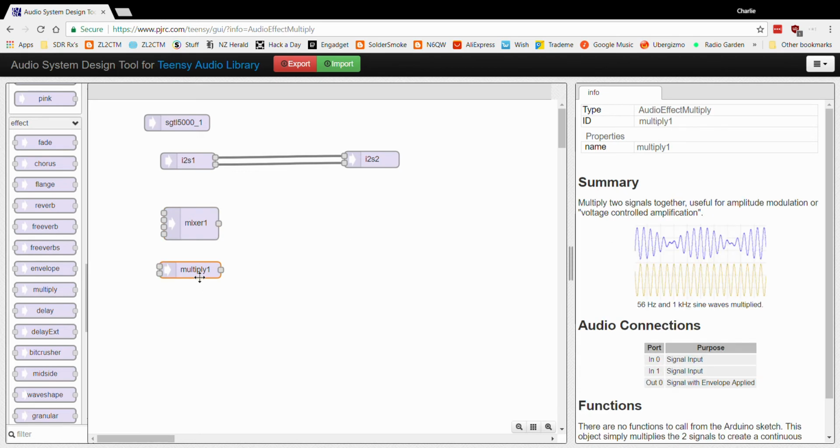And as we saw there with the multiply, we're not going to use that initially, but at some point we may look at playing around with having a 10 kilohertz IF coming in, and then we will, through this particular function here, multiply that by a digital local oscillator, or BFO in this particular case, and we will then bring that 10 kilohertz down to 0 hertz. But initially we won't do that, but just letting you know that if you want to have a look at that early, it's the multiplier we'll be using.